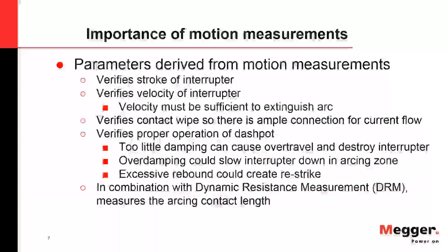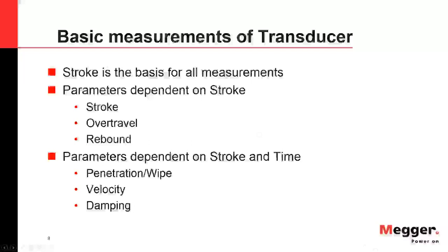And then some other applications, in combination with a dynamic resistance box or something, you can do your dynamic resistance measurements with velocities with the transducer to evaluate the arcing contact length of your SF6 circuit breakers.